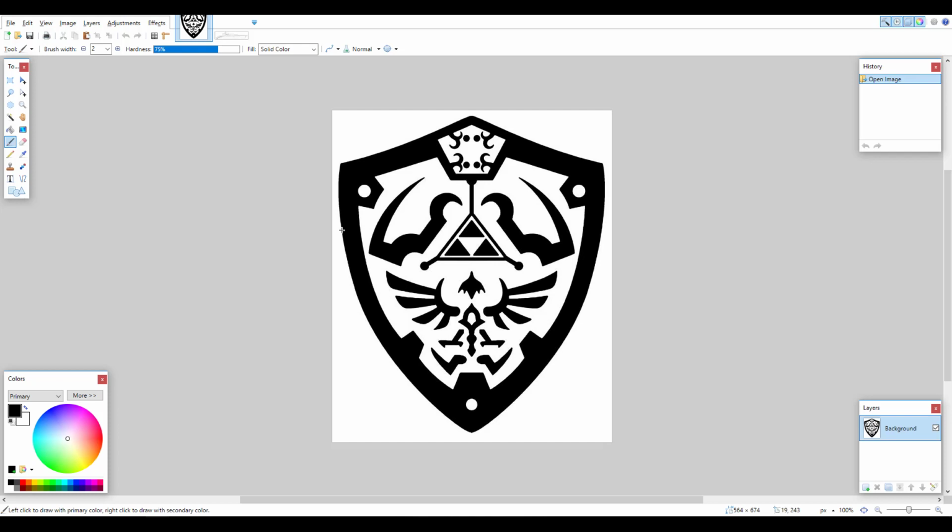And also make sure that the image is not too complex. You don't have too many features, because more features in the logo means more vectors, more lines, and as you know, Fusion doesn't really like complex sketches, and it's going to really affect your performance overall on your machine.